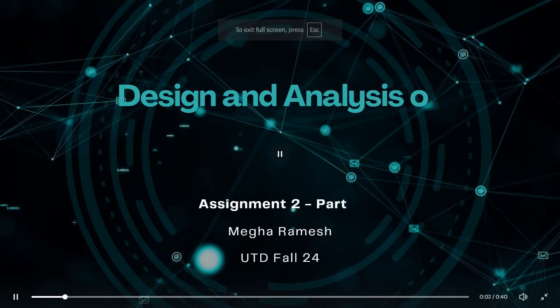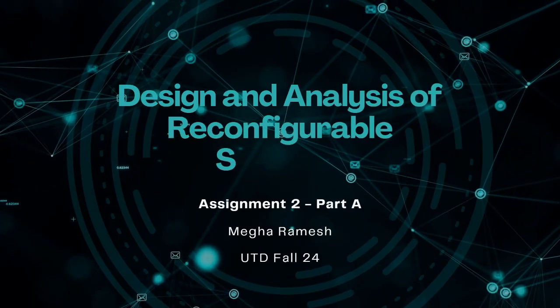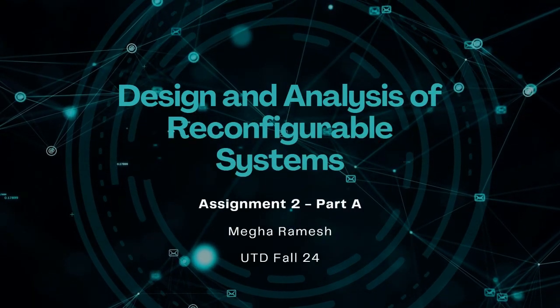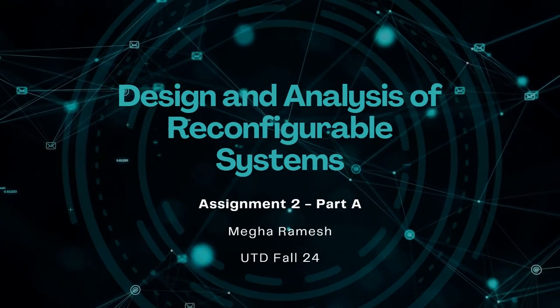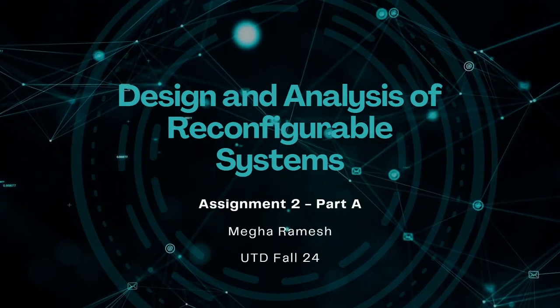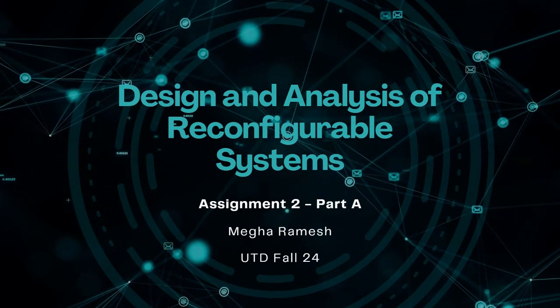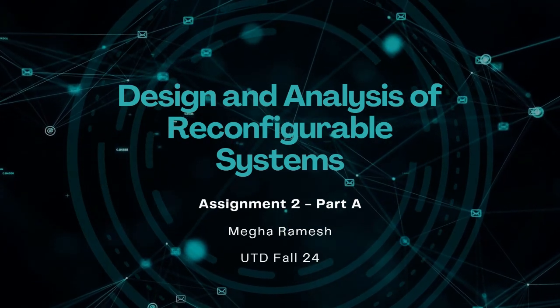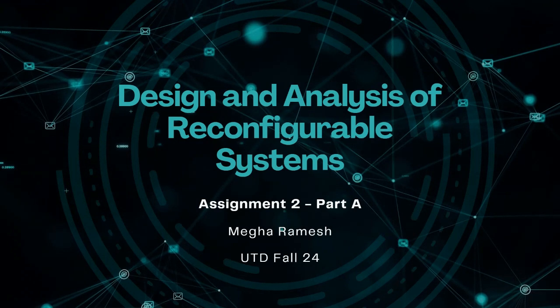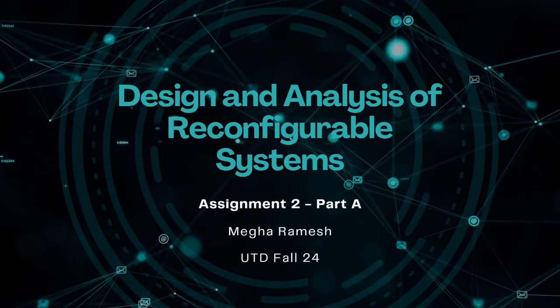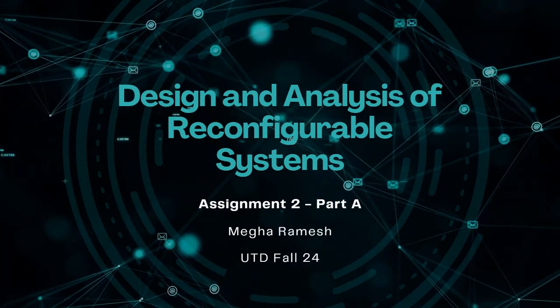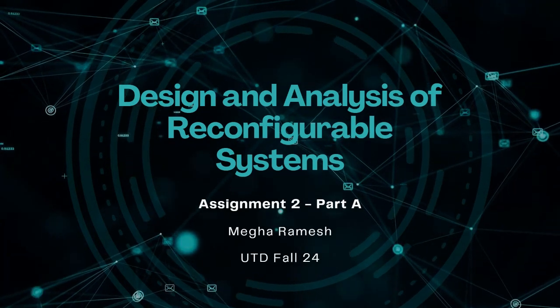I'm Megha Ramesh and I'll be explaining the second assignment of Design and Analysis of Reconfigurable Systems. In this assignment, we will be prototyping on an FPGA board, the Terasic DE1-SoC board, and we will output the 4 MSB of a 32-bit counter to the 4 LEDs of the DE1-SoC prototyping board. By changing a switch on the board, it should count up and down.